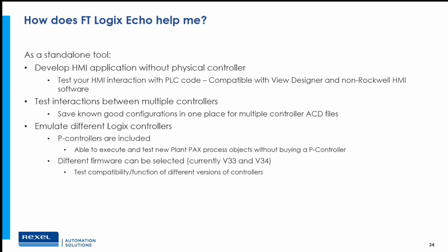And then emulating the different Logix controllers, you do have access to try them all. The P controllers are included. You could try those PlantPAx process objects, see how they execute, see how they might interface with an HMI, and that might be what you need to see before you can verify it in your system, and you don't have to go out and buy all the hardware to do it. And then different firmware: as more and more firmware versions come out, you can check the function of each firmware and see how it interacts, because you can assign each firmware to a different controller and try that out.